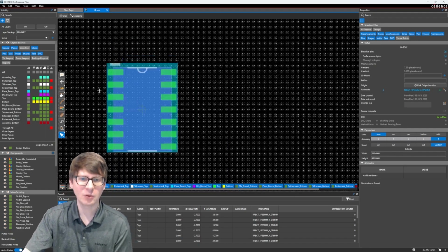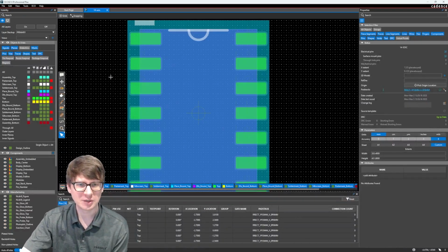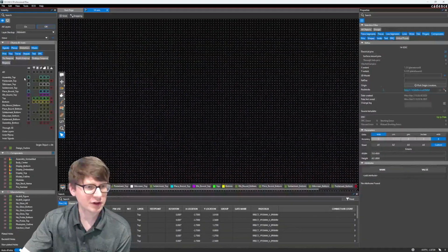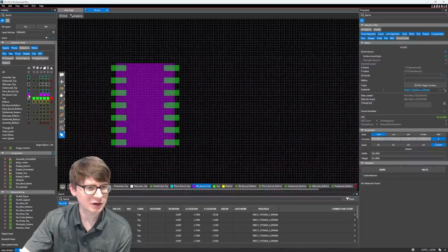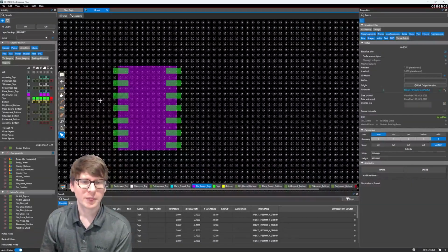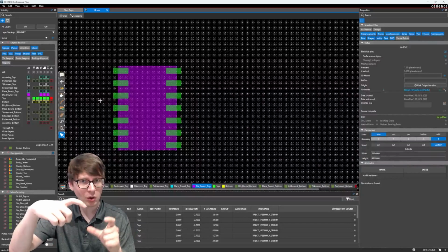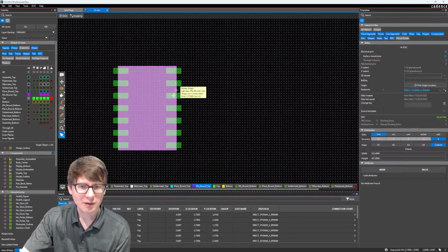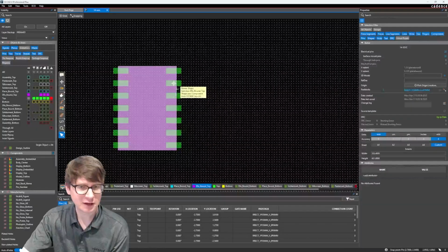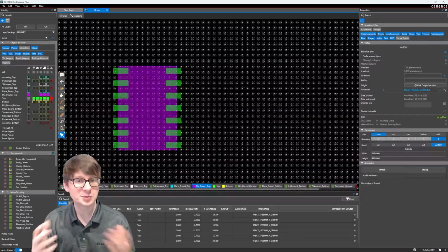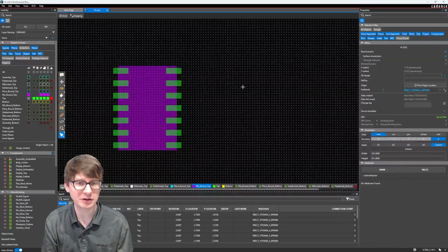All right, let's talk about why we want these different layers to be shaped as they are. So let's start with if we turn everything off except for our top pads and our DFA. So DFA is called the Design for Assembly layer, and it basically encapsulates the whole component so that when we're looking at our Design for Assembly spacing, we can measure from the bounds of a DFA shape to the bounds of another DFA shape.